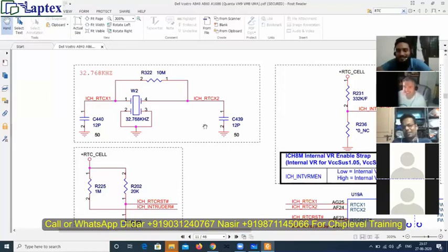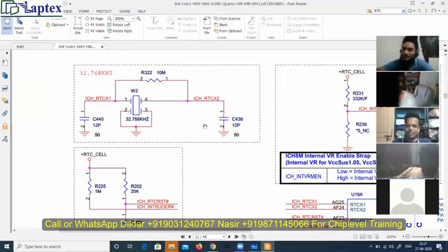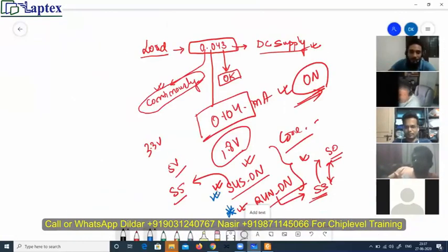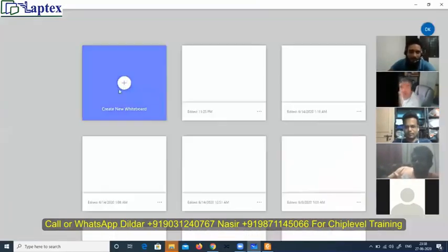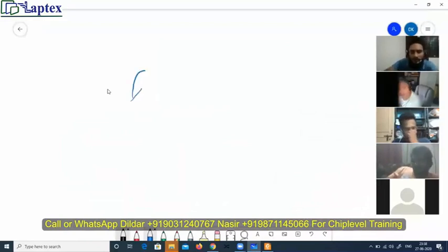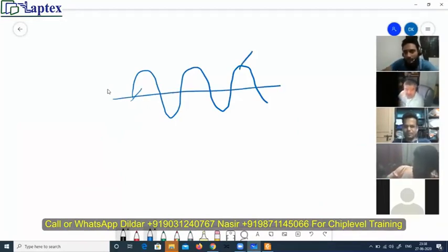Senthil: Actually, what I wanted to say is my previous experience was bad, in so many cases. Sometimes you see 1.2 volt, 1.3 volt supply at the crystal, then you can assume that it is coming good, but that is not a fixed thing. There could be some glitches. See, this is a sinusoidal wave that comes here. You'll see the 32 kilohertz sinusoidal wave, 32.768.